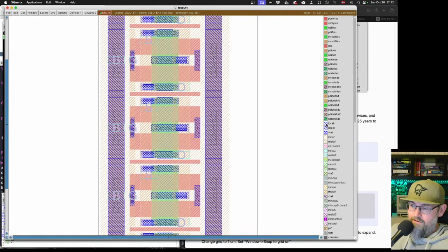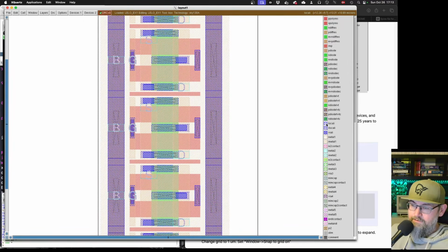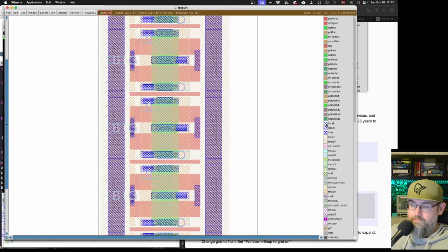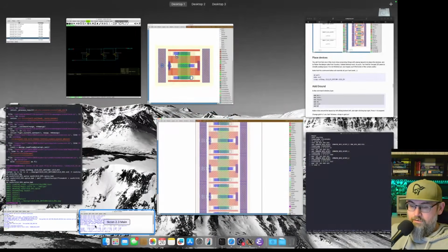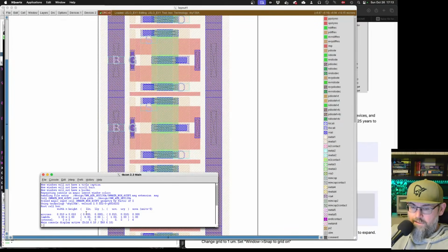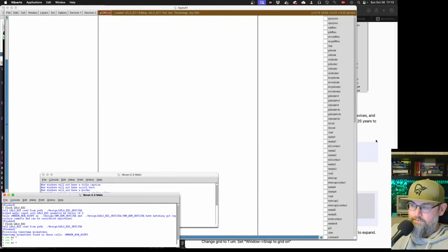Here you can right click to deselect them, left click to select them. You can turn the visibility on and off, and that sometimes helps to make it a bit easier to see what's going on. You can also do those commands from the screen here. See no star, that turns everything off.